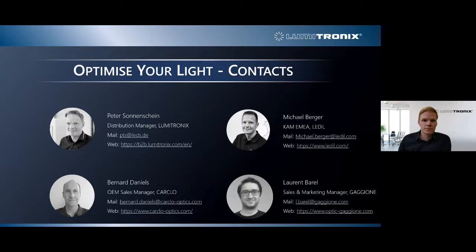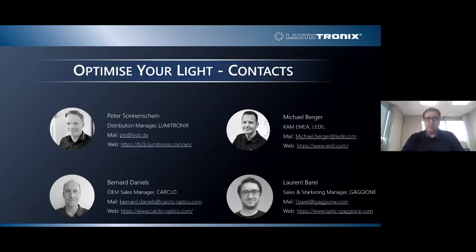Usually, it's not a roadblock or a showstopper for us, because most of the customers and light designers we work with are mostly focusing on the main beam, and within the main beam, they are mostly focused on the D50, the FWHM, which is the beam angle equivalent to 50% of the maximum intensity. So in our experience, we can usually not neglect, but don't overthink too much what's going on outside of the main beam.